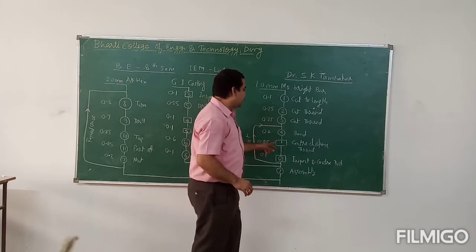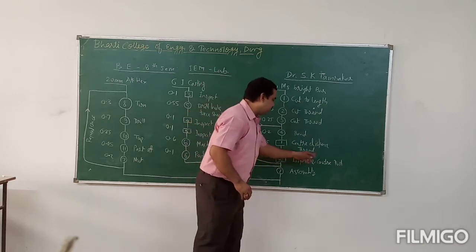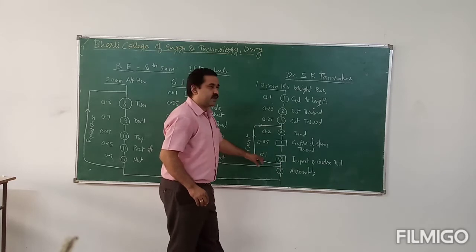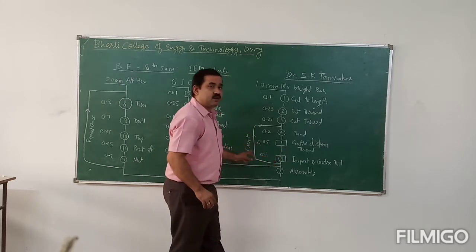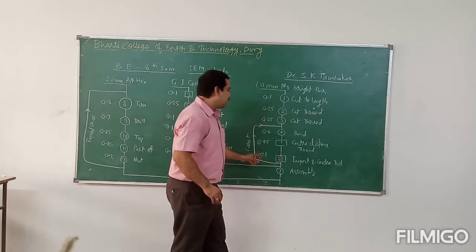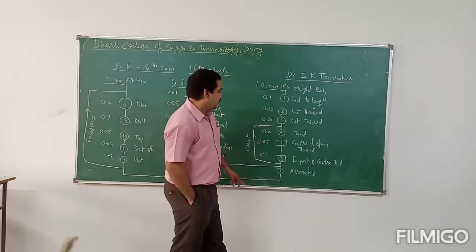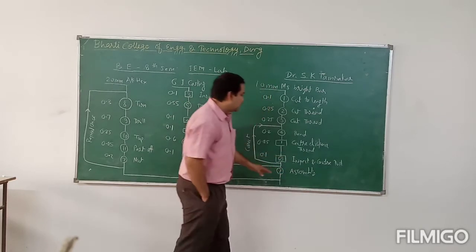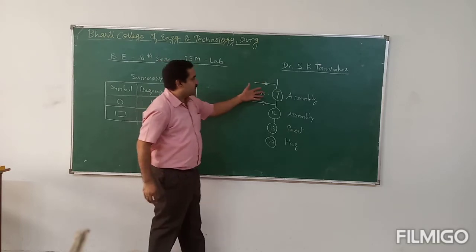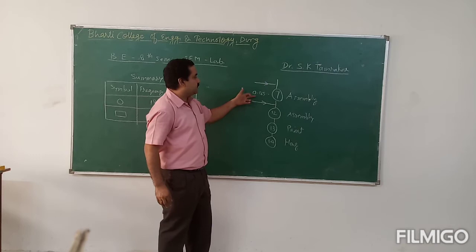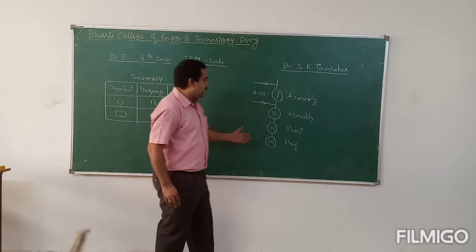Then inspections are there. Central distance of thread inspected, 0.05. And inspection of the central distance again will take 0.1. This cycle is repeated, finding the correct distance. The correct central distance is required here. Then this comes for the assembly. Then we continue the operation. At this assembly, two lines came from this side. This will take 0.05. Then again assembly, and then painting, and then hanging.